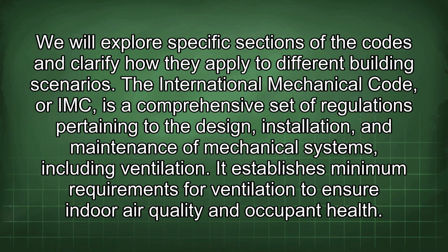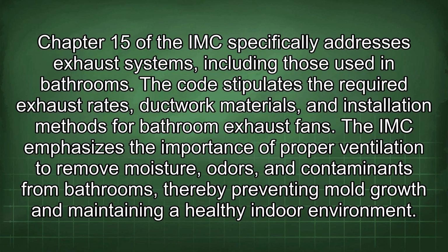The International Mechanical Code, or IMC, is a comprehensive set of regulations pertaining to the design, installation, and maintenance of mechanical systems, including ventilation. It establishes minimum requirements for ventilation to ensure indoor air quality and occupant health. Chapter 15 of the IMC specifically addresses exhaust systems, including those used in bathrooms. The code stipulates the required exhaust rates, ductwork materials, and installation methods for bathroom exhaust fans.